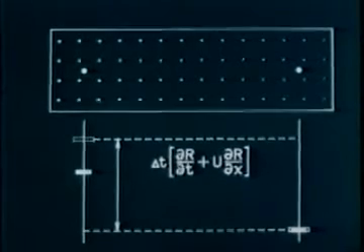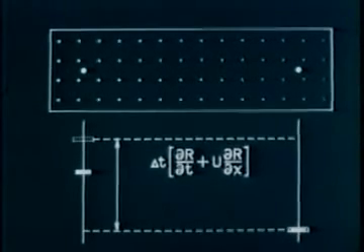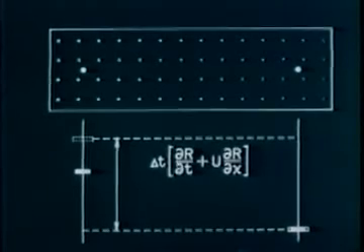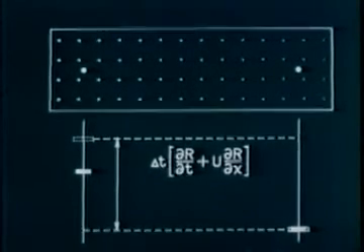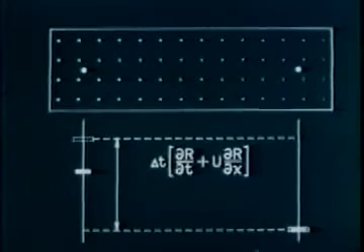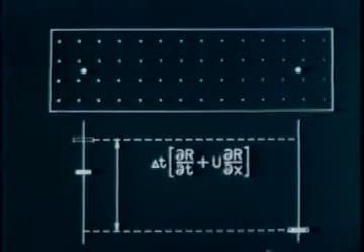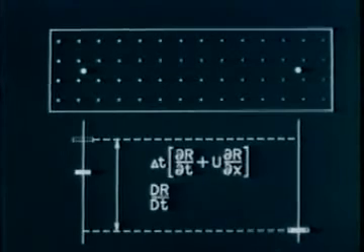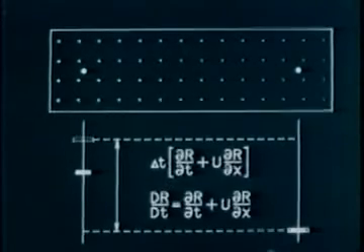The material or substantial derivative is the name given to the expression multiplying the time difference. This is simply the rate of change with respect to time seen by the material point as it passes the laboratory point, expressed in laboratory coordinates. We emphasize that the material derivative is the rate of change seen by a material point as it passes a laboratory point, but expressed in laboratory coordinates. In vector notation, the velocity times the gradient in its direction can be written as the scalar product of velocity and the gradient.